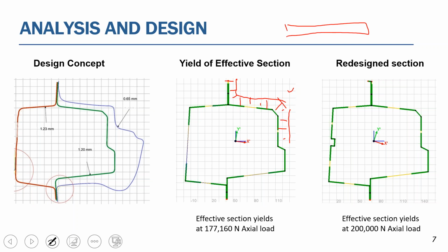If we have a beam, let's just use a very artificial case here. Here's a beam that's supported at its ends and loaded in the middle. So it has a bending moment that looks something like this. That's the bending moment diagram. We have the same section for the whole length of the beam, but we would do the analysis where the moment is the maximum. So we would have to come in with some knowledge of the external loading of the beam, and that's where we would cut our section, where the moment is the greatest.